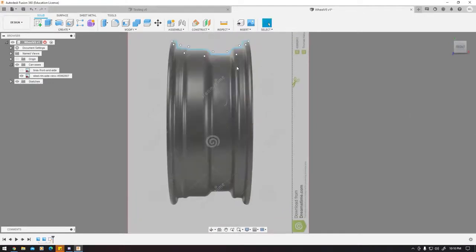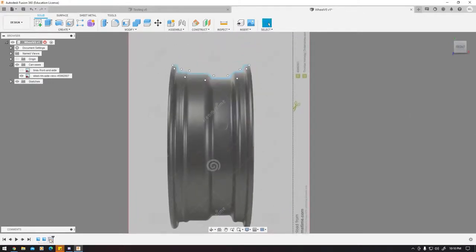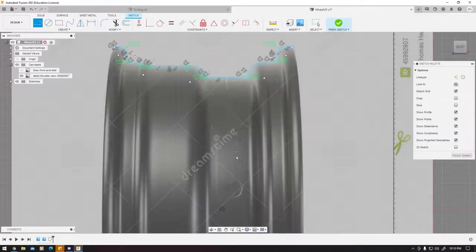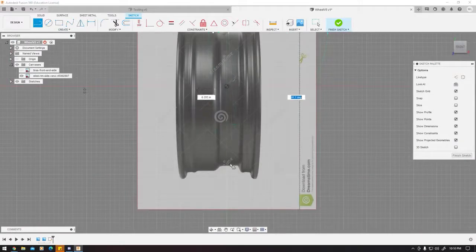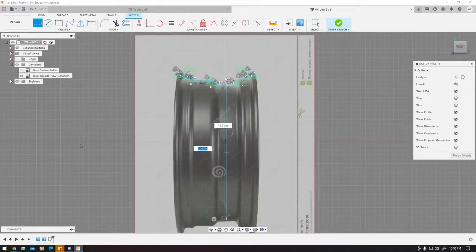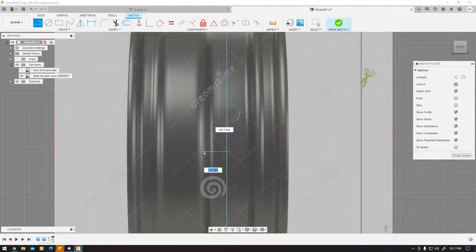So instead of that, I'm going to go back into my drawing. I'm going to go to my timeline, double click on my sketch, make one line from the top right here to the bottom, where I estimate where my next lines are going to be from the top. And then I'm going to go to line again, and it'll automatically find where the midpoint is. So where the triangle symbol is, I click there, make a line right there. I can delete the original line and just turn this line into construction.